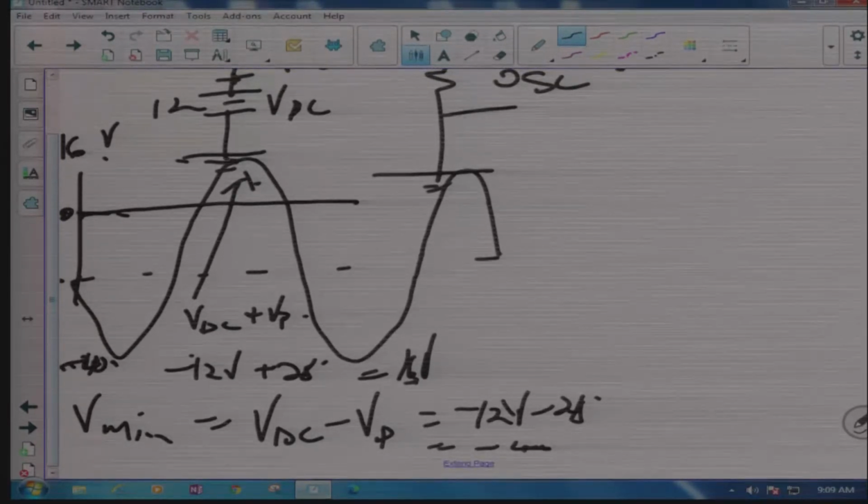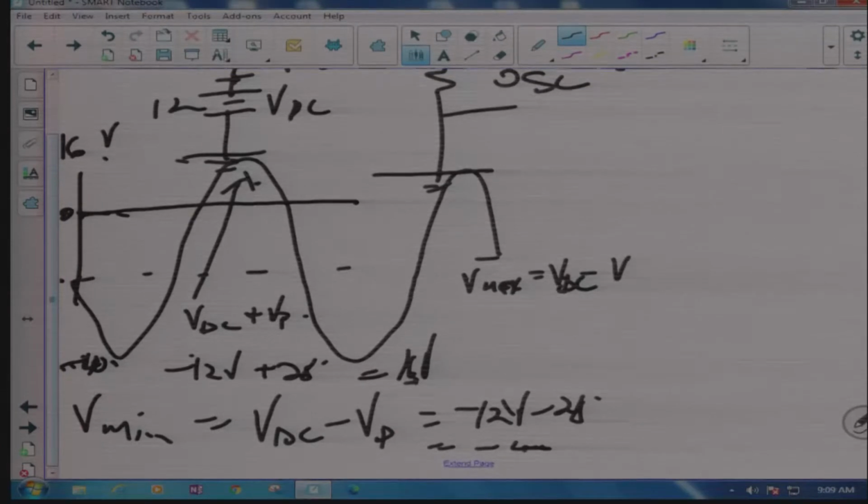Now, what did we look at? We looked at a circuit whereby we have two sources of supply which has got DC and has got AC. So always be careful. Your two formulas are straightforward. V maximum is equals to VDC plus V peak, sorry. Plus V peak.